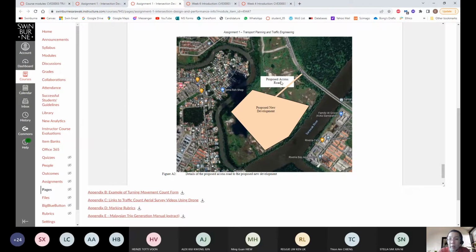Let's say this is 7 meter plus 7 meter on 2 sides, so that'll be 14 meter, plus the median width. Let's say median width, give it 5 meter. I don't know what the width is here, but you can just give it 5 meter, or you can measure it if you want to. So that would total up to 14 plus 5, about 19, 20 meter.